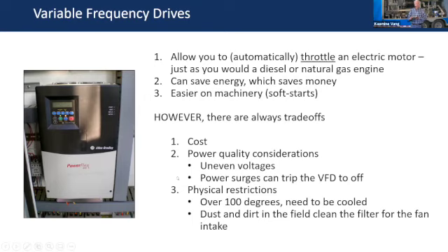Also, for physical restrictions, VFDs are not real fond of 100-plus degree temperatures out in the field. If it's dusty and dirty, a lot of times you have to put a cooler on there to make them work properly. Certainly they have to be encased in a box with a fan and a filter that has to be cleaned periodically. There are a lot of little things with VFDs that you have to deal with when you put them in, but they can save a tremendous amount of energy in the right situations.